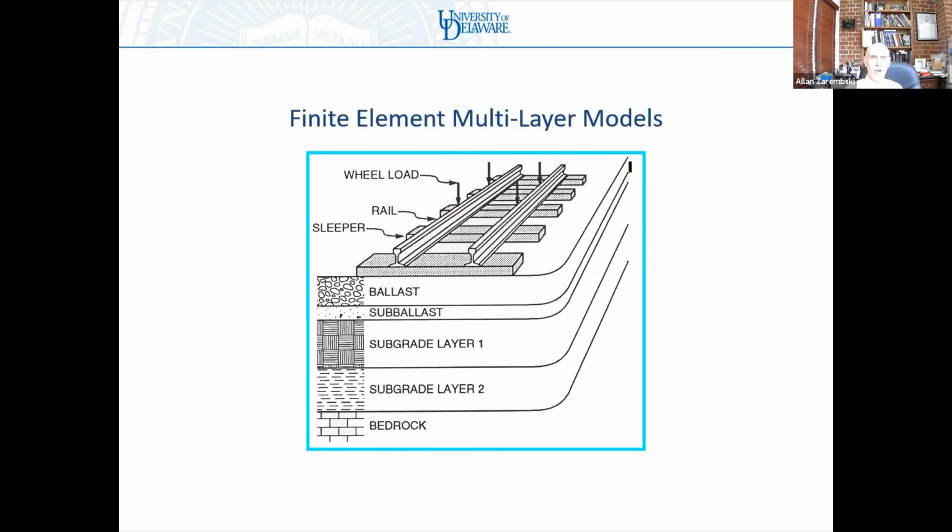And then, of course, there are the multi-layer finite element models, of which there are dozens of these models out there. There have been some models that have been developed over the course of the last 30 or 40 years, which are actually quite good and now allow you to actually have a ballast, a subballast, and multiple subgrade layers. But you need to have a very good knowledge of the properties of the ballast.